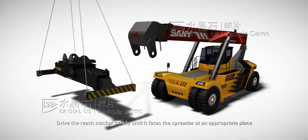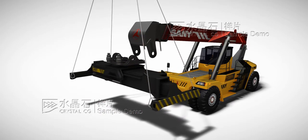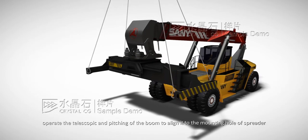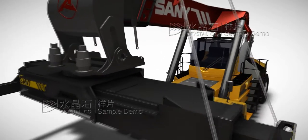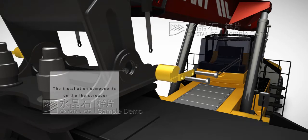Drive the Reachstacker slowly until it faces the spreader at an appropriate place. After the assembling direction is in control, operate the telescopic and pitching of the boom to align it to the mounting hole of spreader. Do not lower the boom by force in alignment, or the crane may tip over because of the impact.